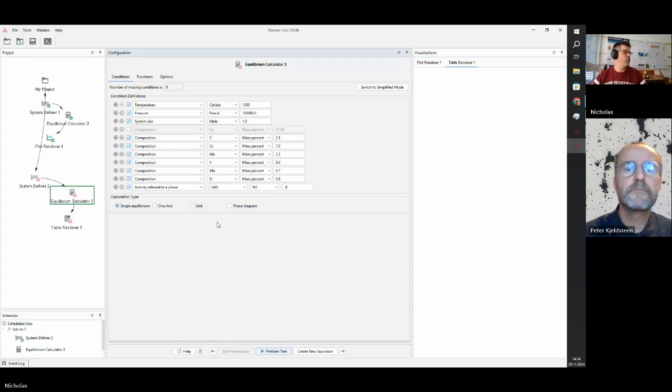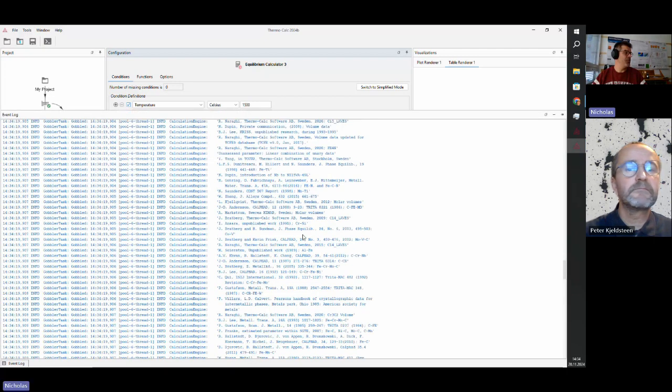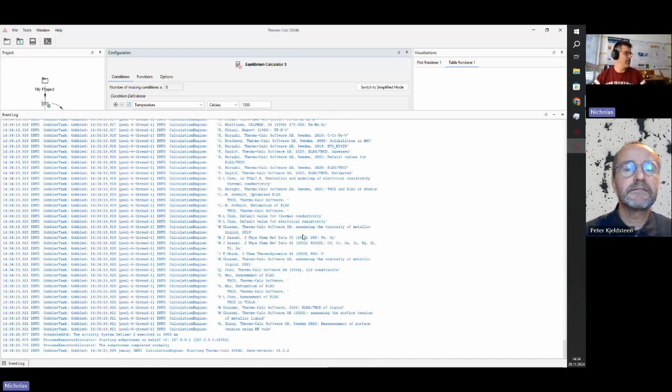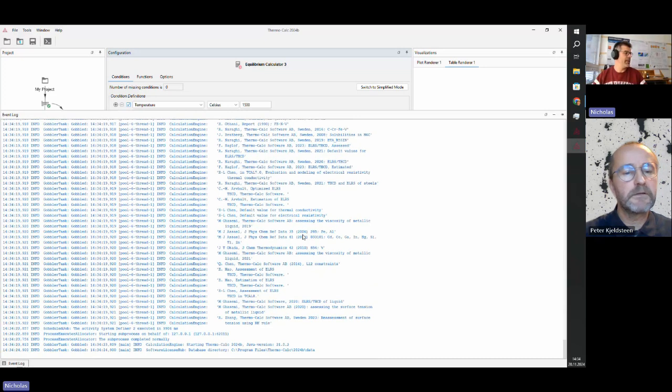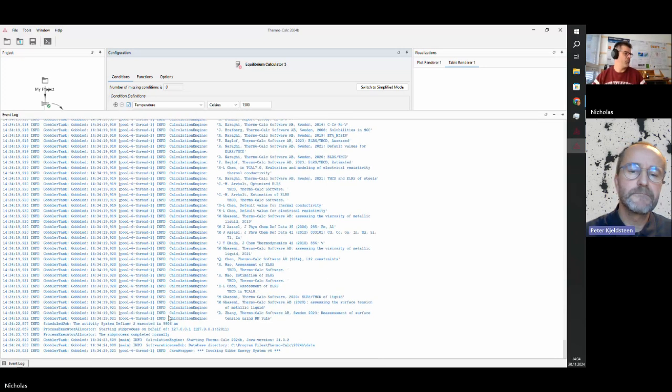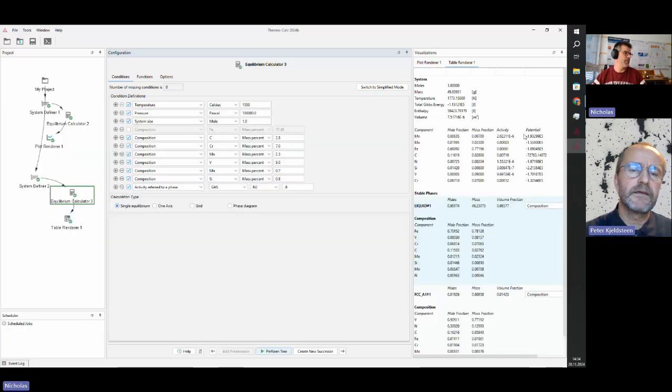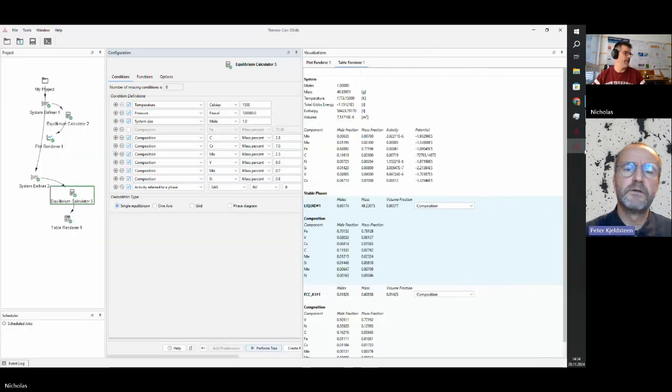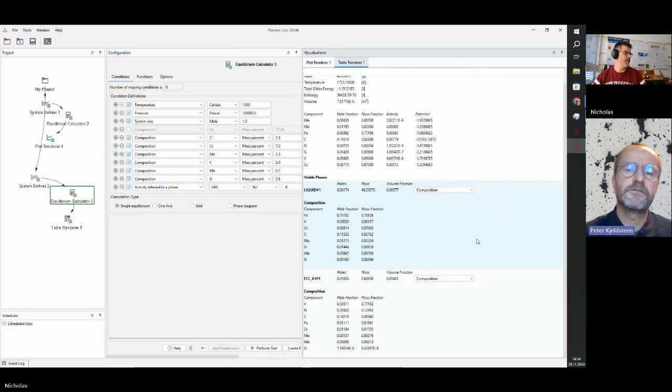Now, because I've added nitrogen, he has to read through the database again and reassemble all the functions. Then he does the calculation, but it should be a couple of seconds. As I remember, we were also able to measure the nitrogen content in the steel afterwards. Interesting, we were some way above 1000 ppm, so more than 0.1%.